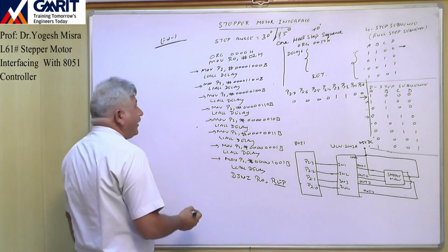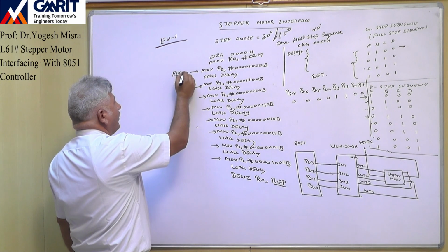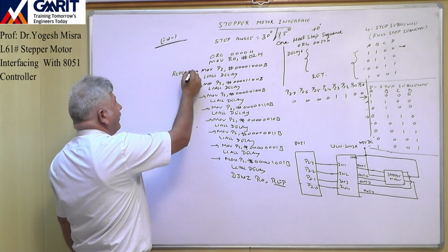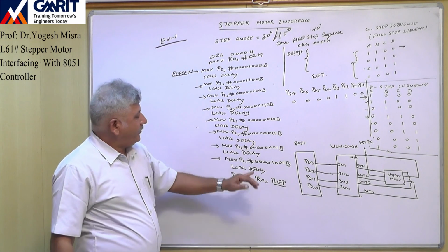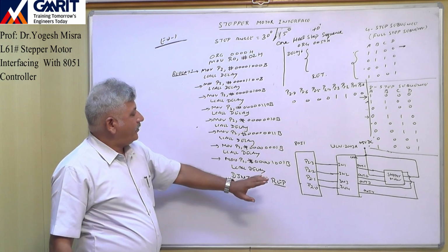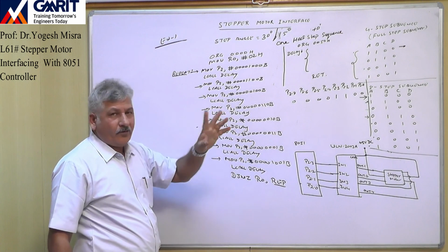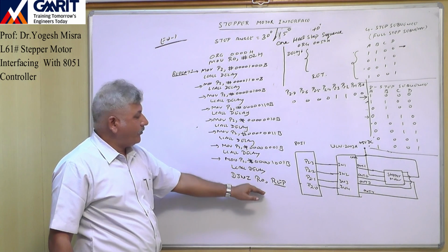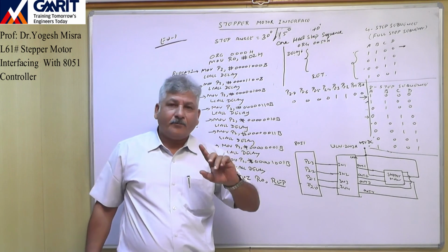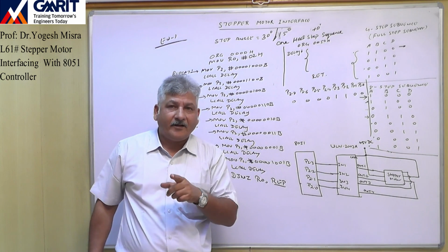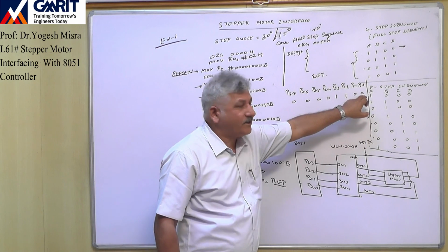Okay, and repeat is here. So with this set of instructions, R0 will become 0 after running this loop 2 times. So when we come out of the loop, by that time the motor has completed 240 degree. Now another 15 degree is required. So simply we send only this sequence.